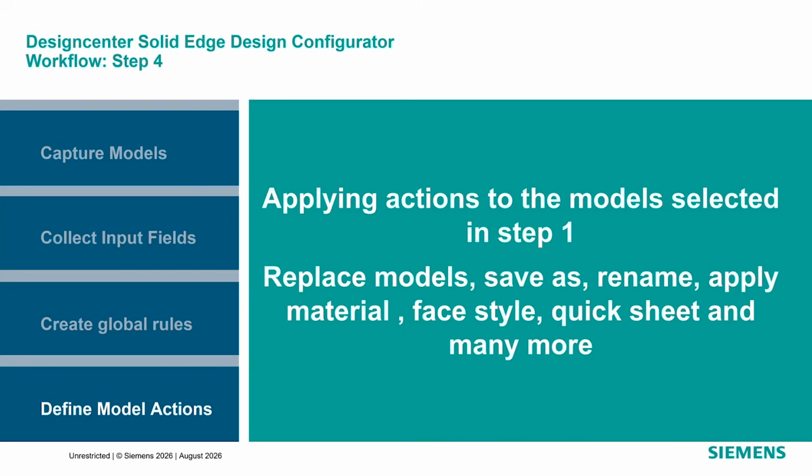So depending on the design, the action can be replacing a model with a new model, saving or renaming a certain model, applying a material, applying a color, changing the variable of the model, changing the properties, creating quick sheet drawings, or performing other supported operations. And we have dozens of model actions available for you. Conditions can be set to when these model actions are run, or they can also be suppressed at any time.